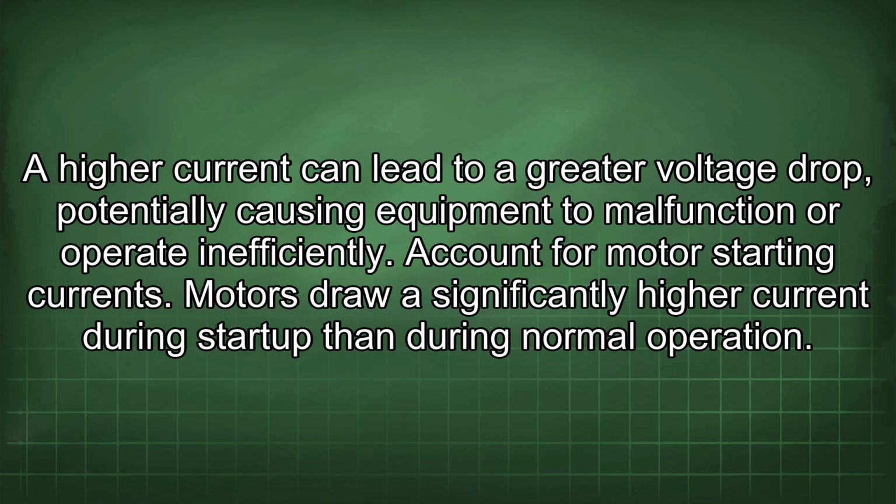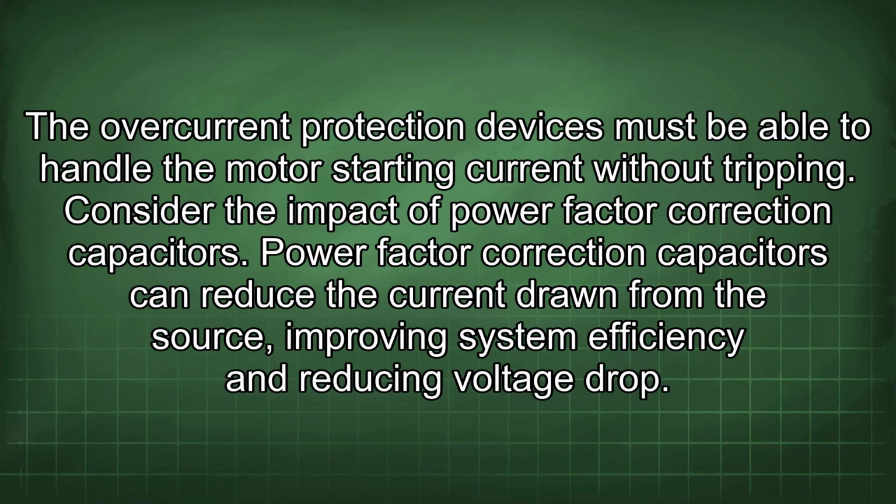Account for motor starting currents. Motors draw a significantly higher current during startup than during normal operation. The overcurrent protection devices must be able to handle the motor starting current without tripping.